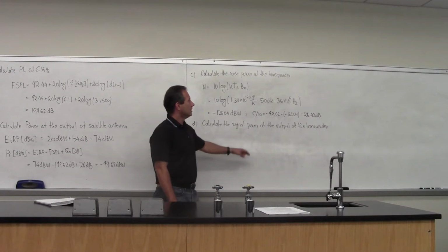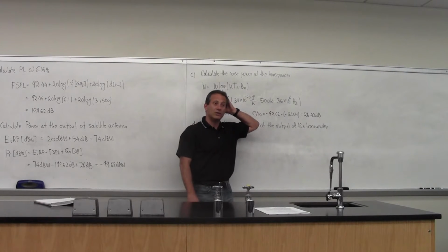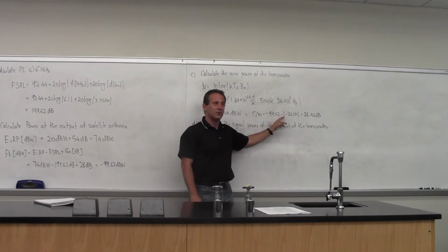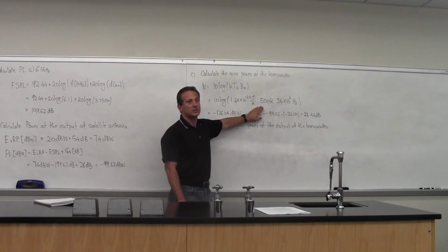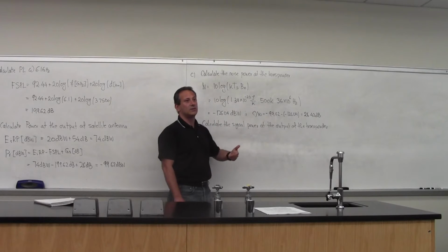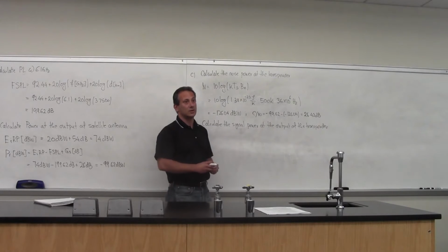As a matter of fact, this is the best you can do, and it occurs only if you don't drive the transponder closer to saturation, and the only impairment that you have is the noise. If you try to amplify and drive the amplifier into saturation, in addition to the noise coming from the system noise temperature, you're going to have intermodulation products that will fall within the same band with the transponder. And this will degrade your signal to noise.